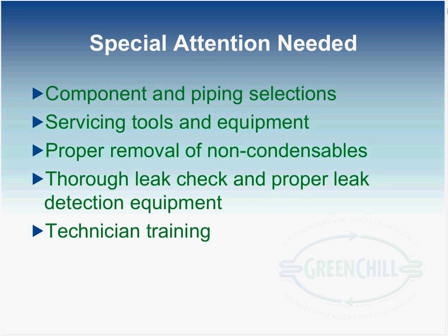Next, on leak checking, it's important to have a leak-free system, even on the CO2 side. A small pinhole leak in a CO2 system can grow quickly just due to the magnitude of the pressures that the CO2 is operating at. So a robust leak check is important. And the proper training of the technicians.